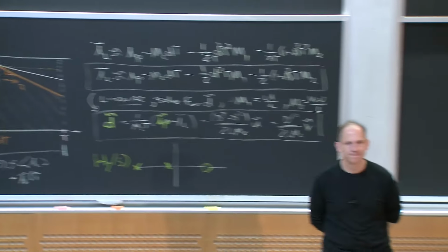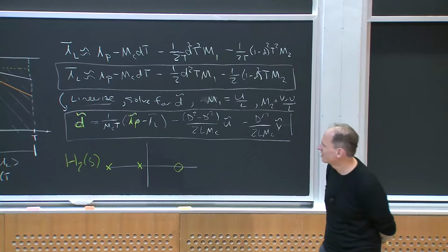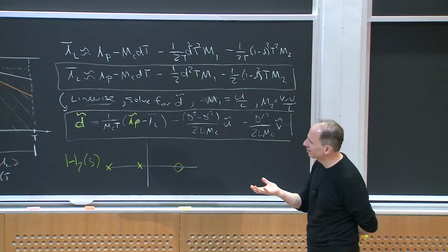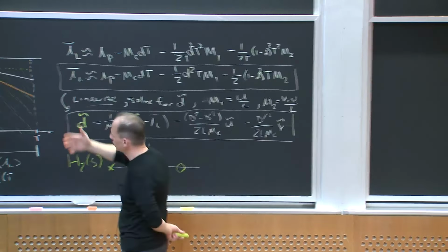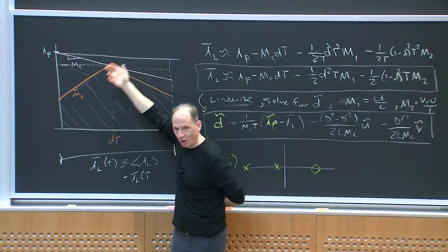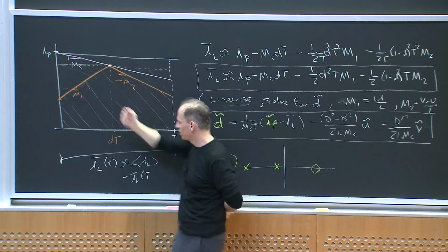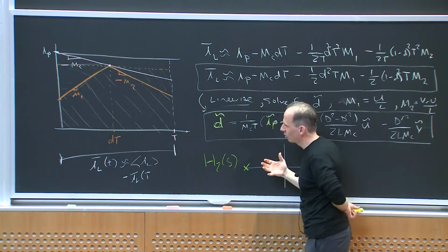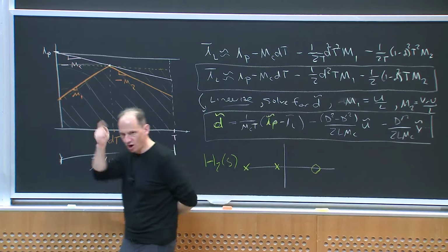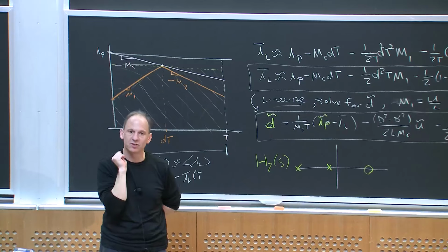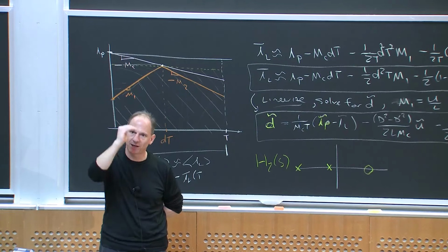Why? Because the way people like to think of it is this inner loop is making the current do what you want, and hence the dominant pole is more or less governed by how the current from that inductor feeds into the output capacitor and charges it up and down.